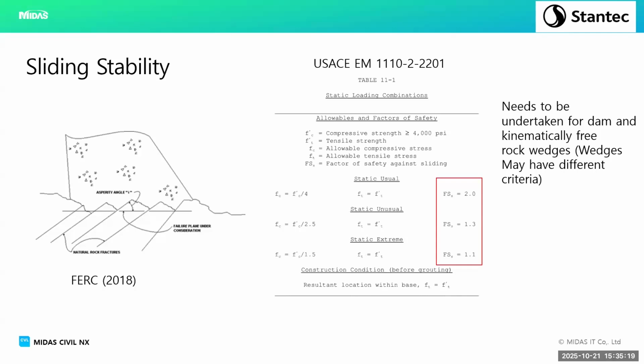Basically, in dams, what we do is we take a look at your peak shear strengths and your residual shear strengths. And we check it, and this is for gravity dams specifically, we get different factors of safety, and there are different requirements in the guides.